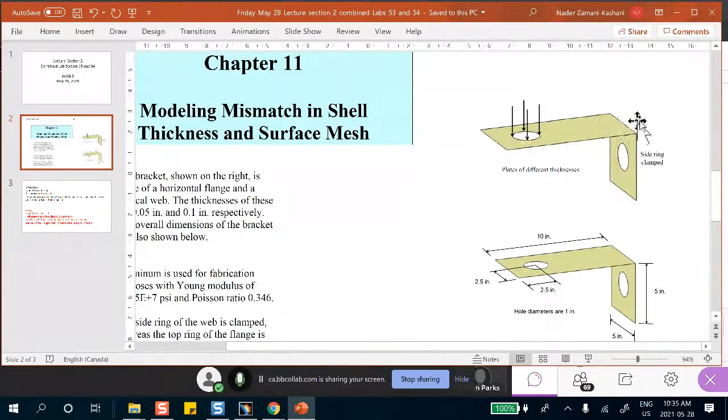There is a plane of symmetry here, right this way and down. So basically, you need to model half of this, and you have to if this problem is given to you for assessment purposes. Now in the book, not only is it done differently, using surface extraction, but symmetry is also not used. Today when I do the book's approach, I will again use symmetry.